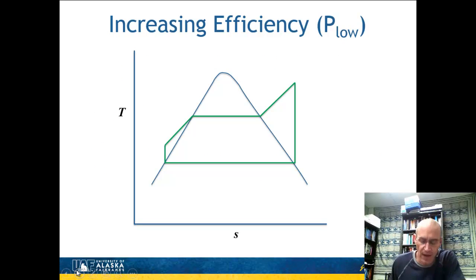All right, so let's look at the traditional Rankine cycle. I've got an ideal Rankine cycle here. So we have this point right over here, which is the condenser outlet we traditionally call point 1. We go through a pump up to point 2 right there, and then we heat all the way up to this, which would be point 3, and then this is our turbine down to point 4. So that's the kind of traditional Rankine cycle. I've got vertical lines on the TS diagram, being that this is an isentropic pump and turbine. And so we'll go ahead and just stick with those for now.